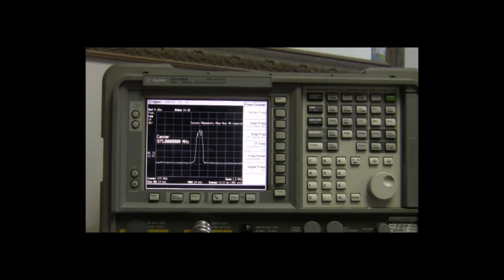In the normal environment, what we would do, we would test it at the bottom end of the L-band range, say around 950, and we would take it up to the higher range, 1250, and make sure that the frequency generated by the modem is consistent with what we're asking. In this particular case, it's just a short example of how to use the interface. So I'll conclude everything is fine, and we'll call it done.